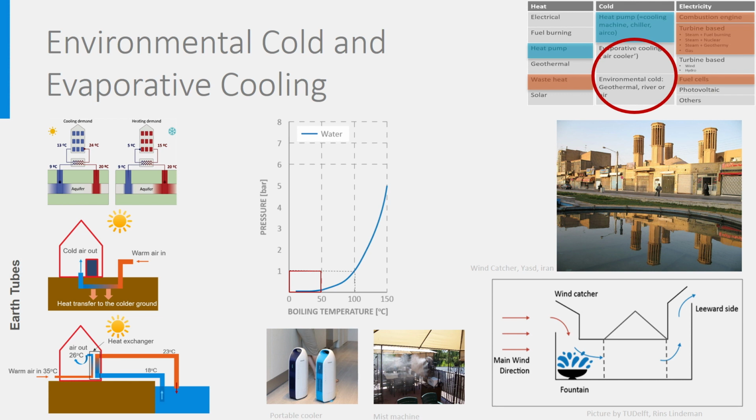When used in combination with a fountain or a spray, see figure below, it is quite effective in cooling warm, dry air. Evaporative cooling is very efficient in terms of energy usage, and we can by approximation neglect the energy use of the pump, by which primary energy and CO2 emissions are zero. However, it is not applicable in humid countries as the air there is already close to saturation.